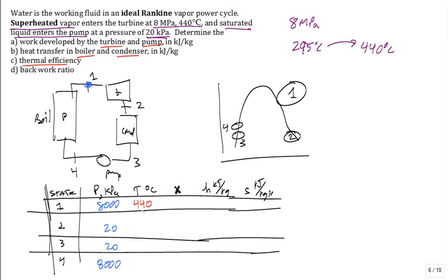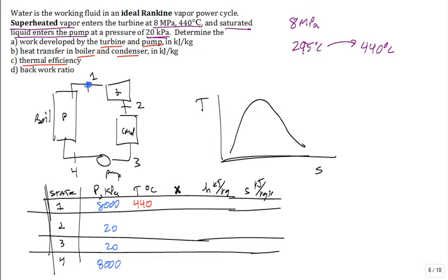Now, most of the time, when you condense on a temperature entropy diagram, and you have some slightly superheated steam, when you go through the turbine before you get into the condenser, it's still a high quality steam at state 2. But let's say you really superheated it. There's a possibility it could be superheated vapor. That's not good for performance.